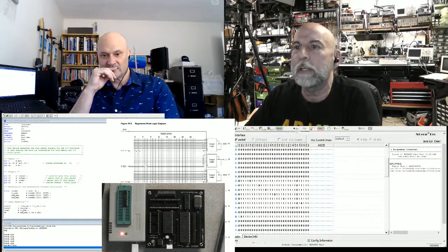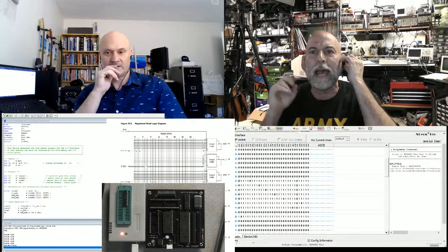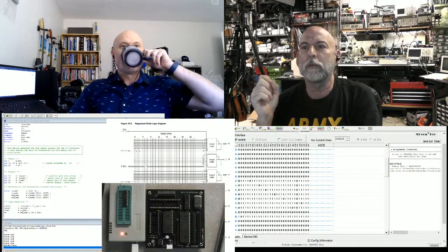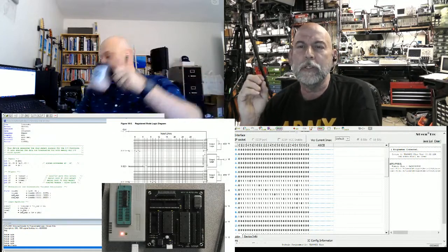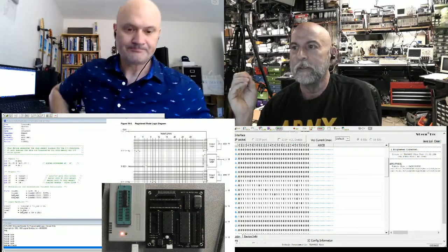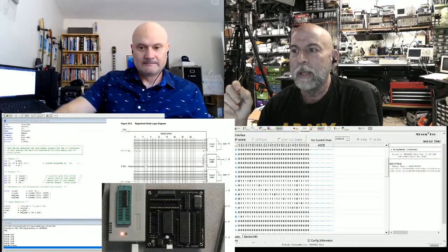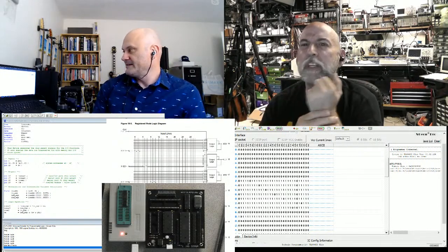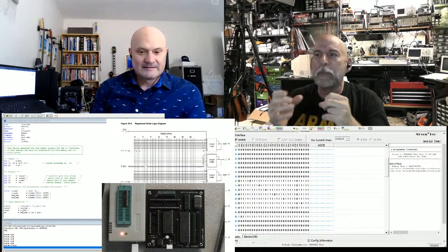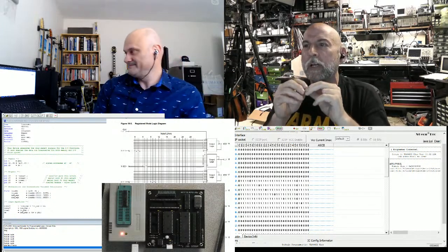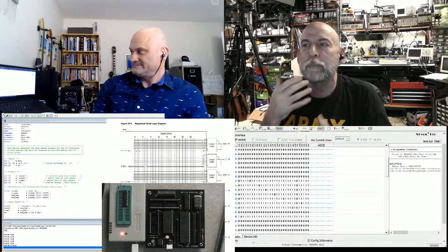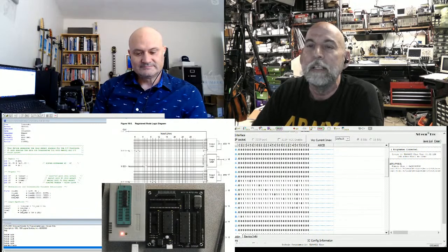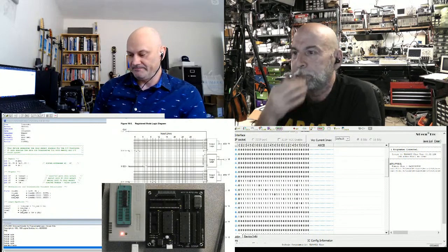And also, I'll say that this family is different. We used to use this as a PAL, which is an AND-OR array. You do the AND function first, then the ORs. We used to do PLAs also, which were OR-AND arrays. But this little part here, like you said, almost preceded FPGAs. My memory is they came out at the same time as the old Xilinx parts. And the Xilinx was basically a big PLD. It had 64 cells in it that basically had 5 terms each, whereas you actually had more terms available per cell in the PLDs that we're showing here today.